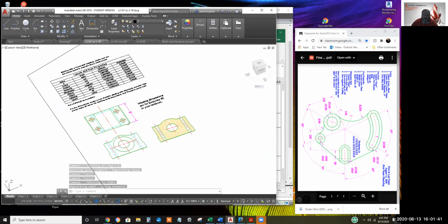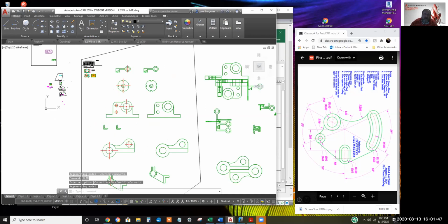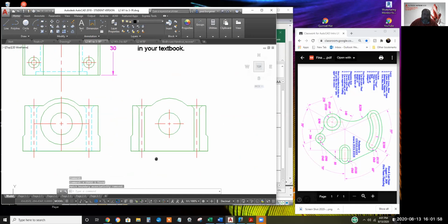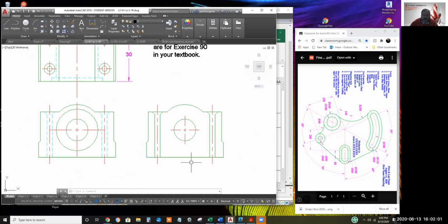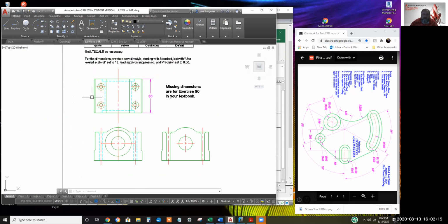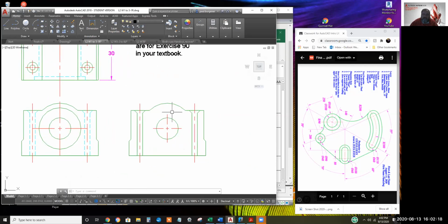And here's the stuff that I showed in the viewport. I'll type plan, enter, enter to look straight down on the XY plane. And we will delete this cross-hatching. I was once told to teach the software, not engineering graphics, but if you slice your object in half with a bandsaw right down the middle, that generates what's called a full section view.